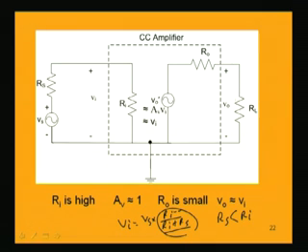That means the load resistance RL will get a voltage equal to Vs, because Vi is almost equal to Vs, and out of Vi only a very small portion is lost here. So the whole voltage we can get at RL. That means we are incorporating a buffer stage, the common collector amplifier, known as a voltage buffer, just to get the source voltage totally at the output.